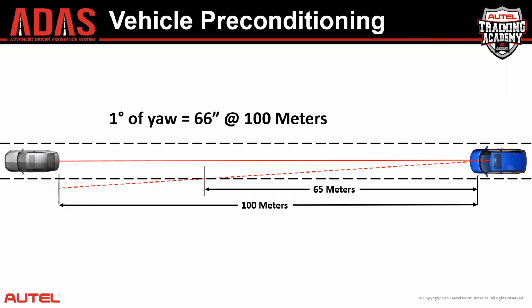This is actually a repeatable phenomena, something that's been in the news recently, of vehicles that are engaging automatic emergency braking when there is no potential for a collision, because either the camera or the radar are looking in the wrong lane. And when they see a vehicle in that lane, they assume it's in the lane in front of our vehicle because we calibrated the camera. The camera trusted us that we were going to follow those preconditioning instructions.